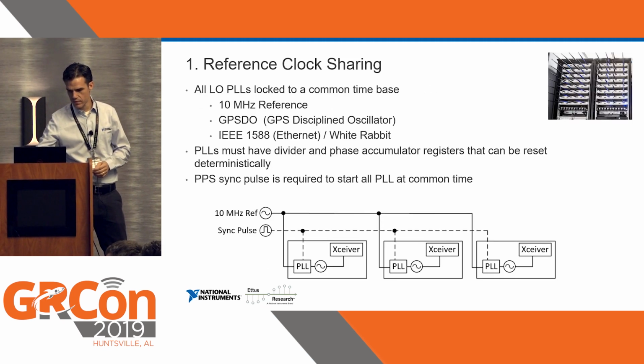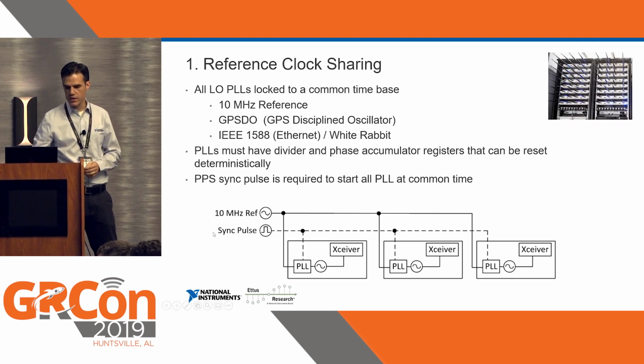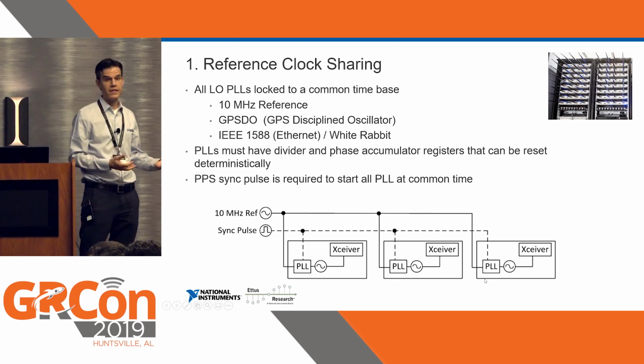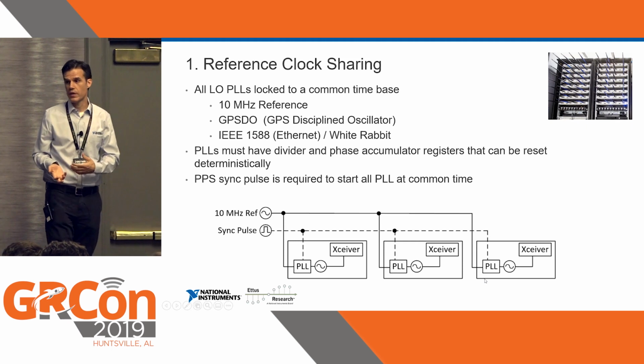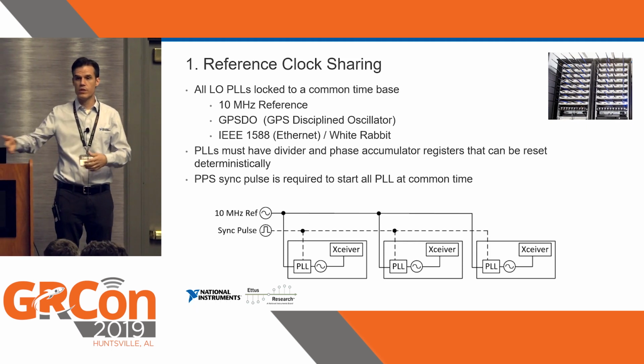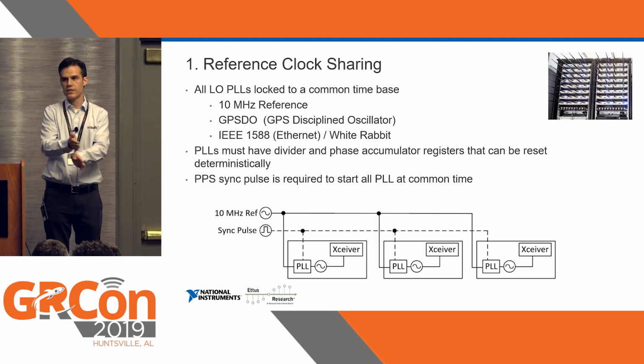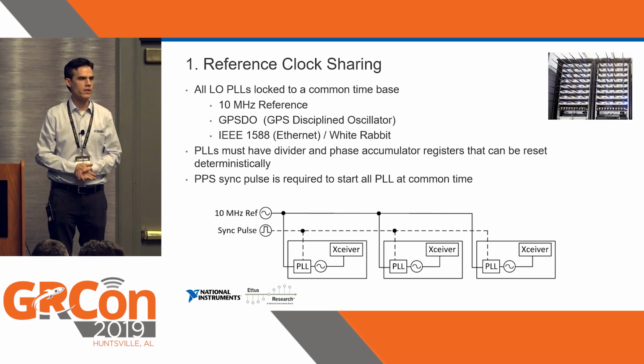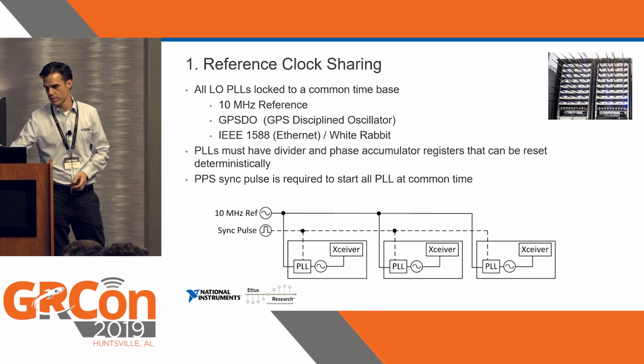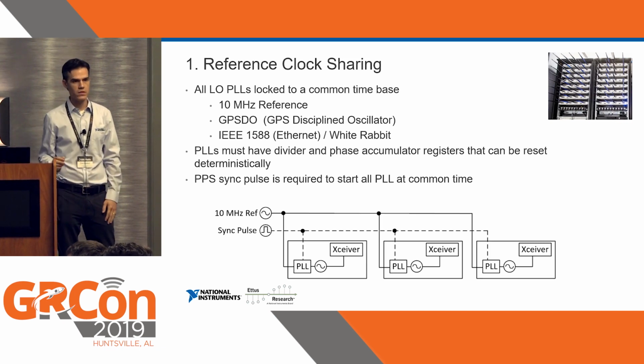And let me go back up one here. You see that each of these devices has its own PLL. And so each PLL has its own phase noise profile, right? They're going to be uncorrelated to each other. So we've aligned the phases of these local oscillators. We haven't done anything to make them coherent to each other in this case. But it is pretty nice because you only have to distribute these two signals.